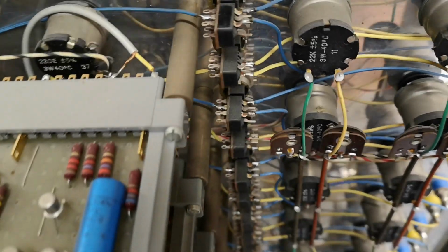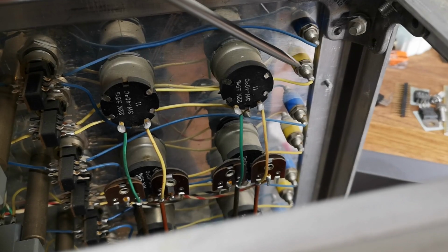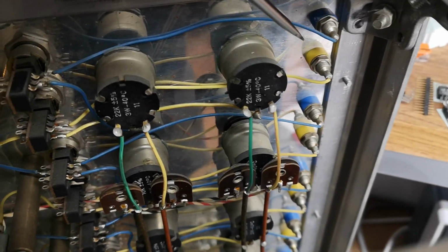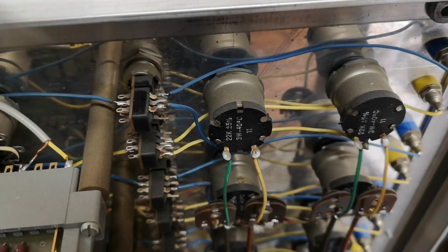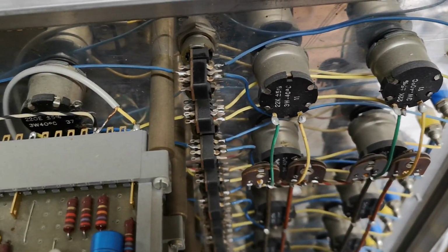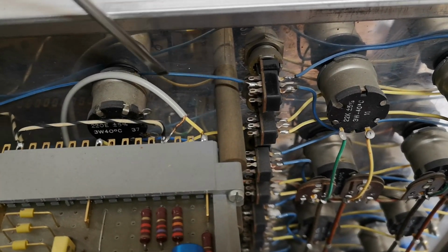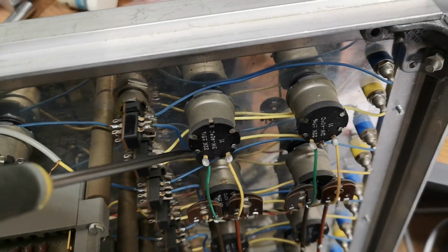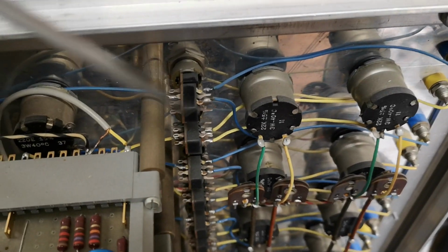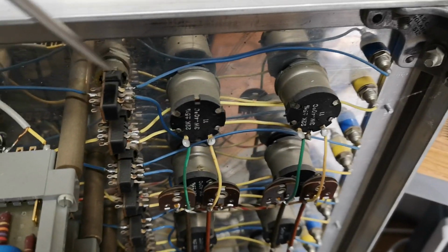Let me show you guys this here, it's easiest to see. This will be the analog inputs from the previous module. An analog input goes to this switch. So if I push this switch, that means whatever I want to control is now connected to my pot, to that one. And if I release the switch, the signal is now connected directly to the input.